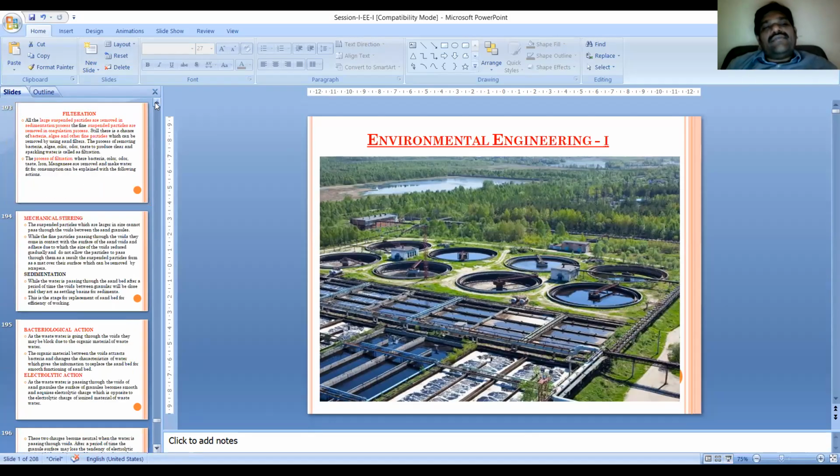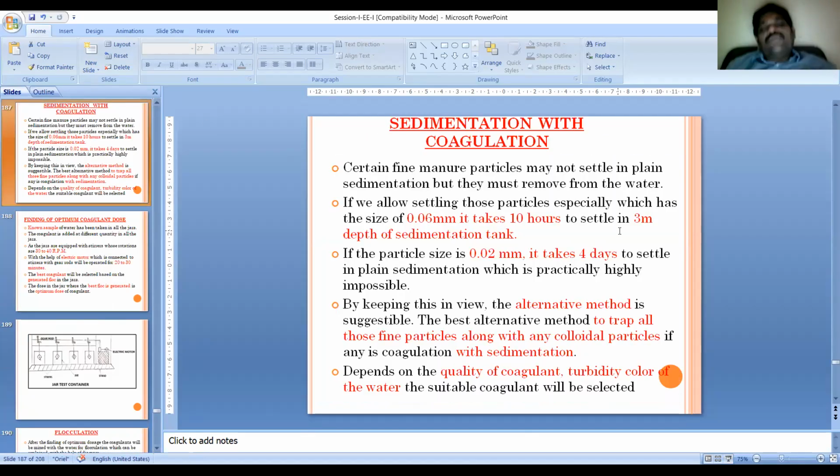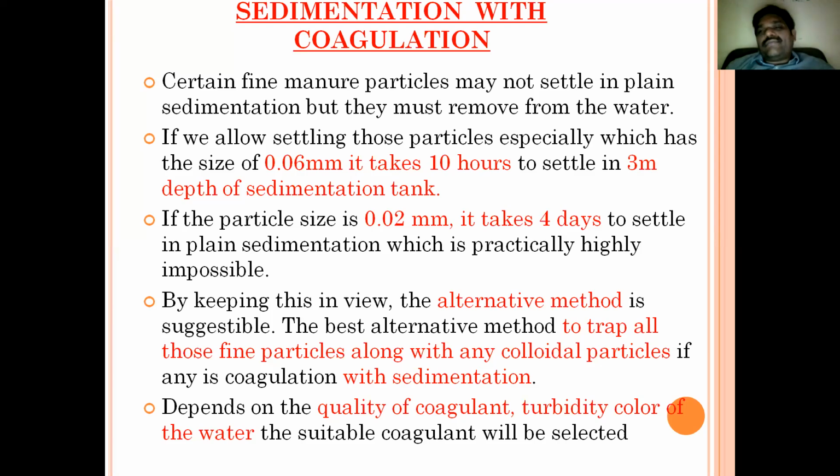Yes, sedimentation with coagulation. Why does it need coagulation? Because in sedimentation, we may not separate, or else we may not treat the fine colloidal particles.